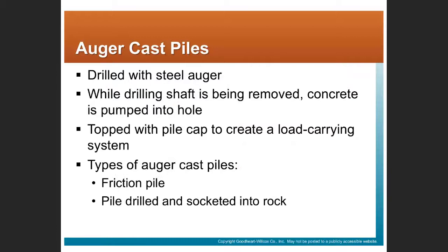Okay, so the things you're looking at there, footings and foundations would apply to residential and small commercial construction. If we are getting into larger structures, more stories, heavier weight, then we have to find some other means to hold up that building, right? Generally speaking, we're going to have to find a means to get down to bedrock.